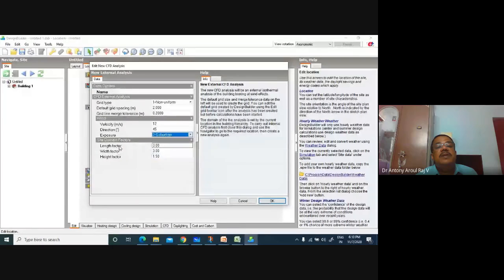So what are the site domain factors? Because here you are having a building, the mesh will be done over the building. Just now we are going to see. What should be the height for which the mesh has to be done? That is what will be given here. It is given as 3, so I can change it to 6.